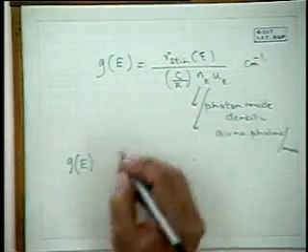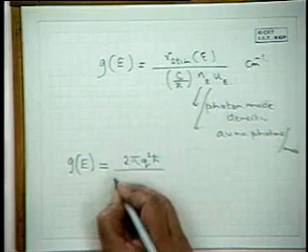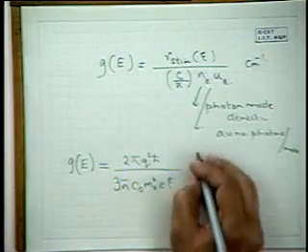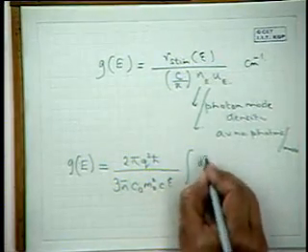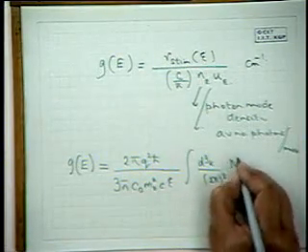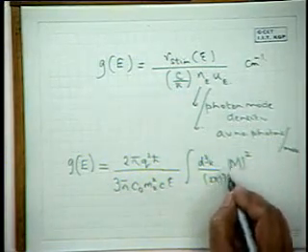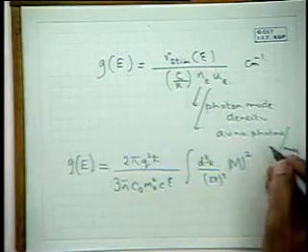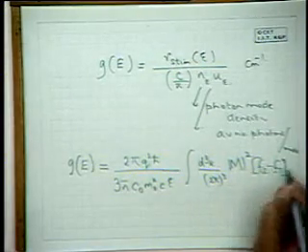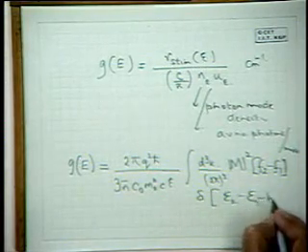From this one can get to the expression which I derived for alpha, so this is just minus alpha, is 2 pi q squared h cross by 3 n bar c0 m0 squared c, integral over k space, this matrix element squared, which will be the momentum matrix element squared for transitions from the conduction band to the valence band, downward transition, so F2 minus F1, and delta E2 minus E1. This is the conservation of energy rule, minus h cross omega.